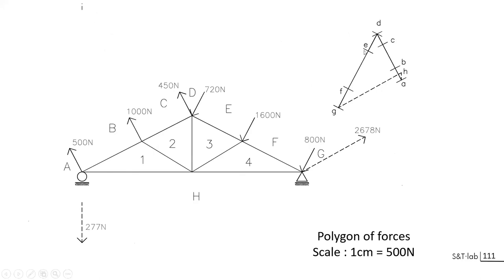So the load line will be here, it will be broken this time, and this is closed with the reaction force that is shown here below. We can move again with adding the other bars and with parallels of each of these bars. For instance, if you have C2 here, you know C, and you have 2 appearing here as an intersection with the vertical passing to 3. And this is an incremental construction that you are able to do.